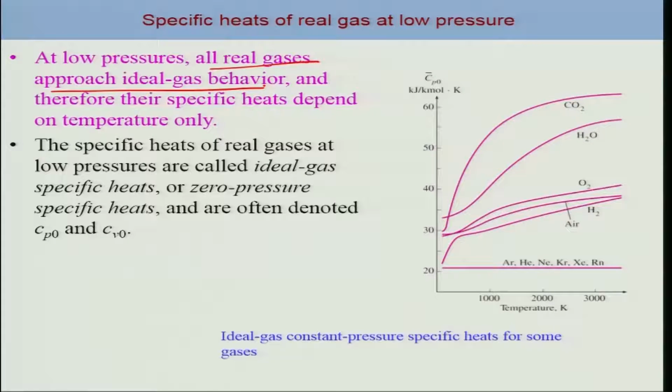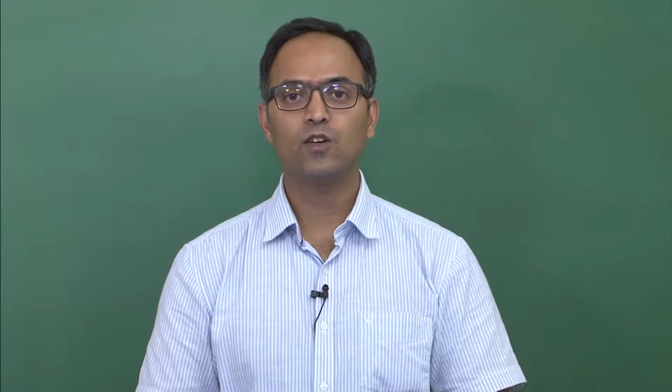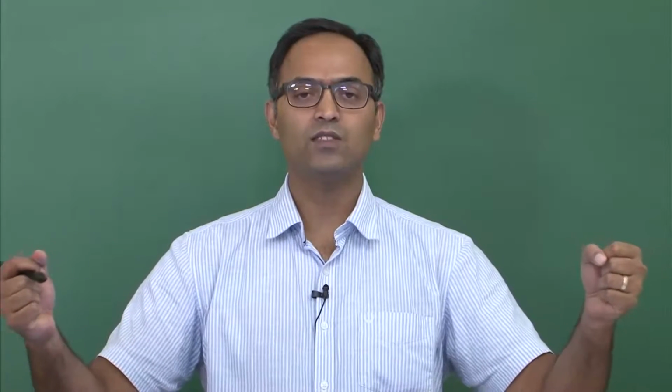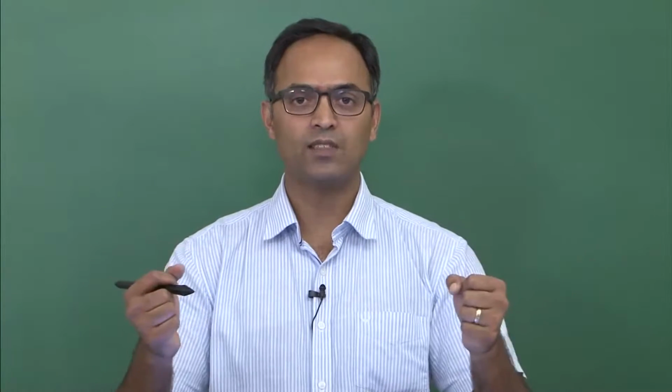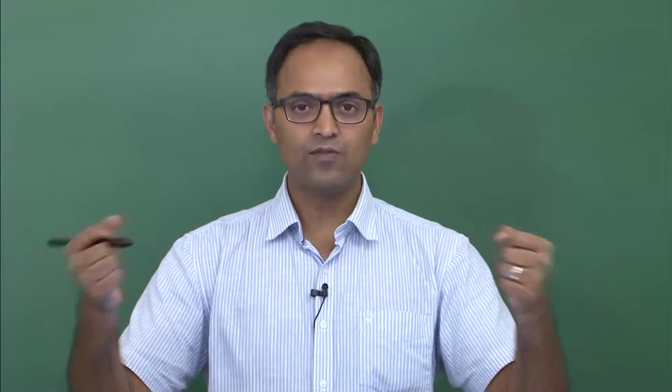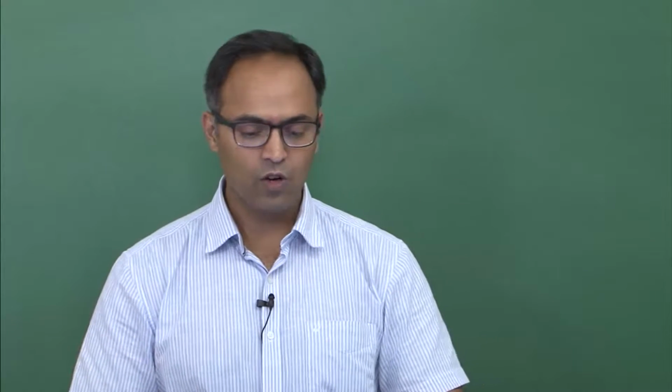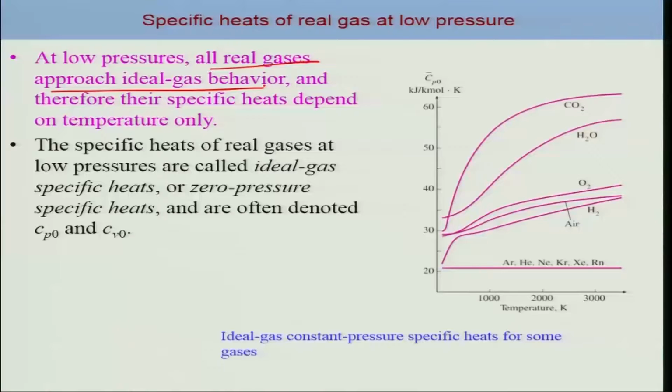At low pressure, gases are at low density, in a sense they are very far from each other, and hence they do not experience each other's presence. So they don't get influenced, and due to that their behavior can be approximated as ideal gas behavior, and thus we are going to make use of the low pressure approximation for the specific heat values of the gases.